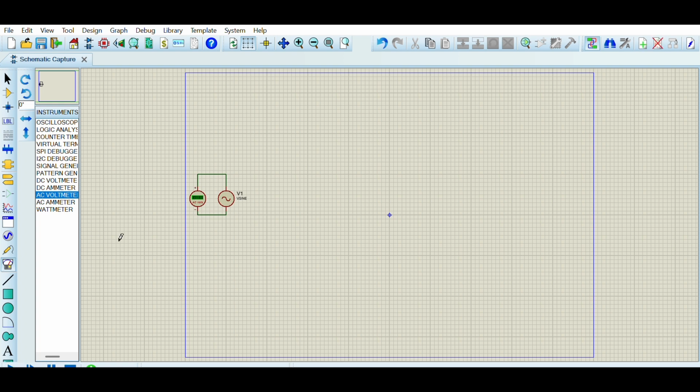Okay, so if you have ever designed or seen a power supply circuit, you know you have to have a bridge rectifier made out of 4 diodes. I'm not gonna explain much on that, but we can just go ahead and place one ourselves. We search diode and we can place the bridge rectifier right about here. Now these are standing upright, so I'm just gonna rotate them. Connect the 4 diodes. Just make it more presentable as well.